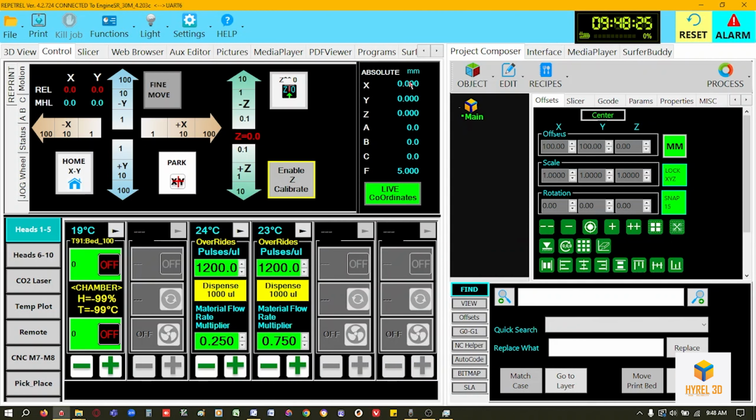Now remember, you need to do your cloning either through the GUI or as stipulated in your G code. That's all explained on the wiki. You do want to remember that cloning heads or parallel printing does not work if you're using M229E1D1 in your header. That's the command that tells us to use the E values generated by the slicer. So you must use M229E0D0 to let us do the flow calculations based on what we said here the nozzle and layer sizes are.